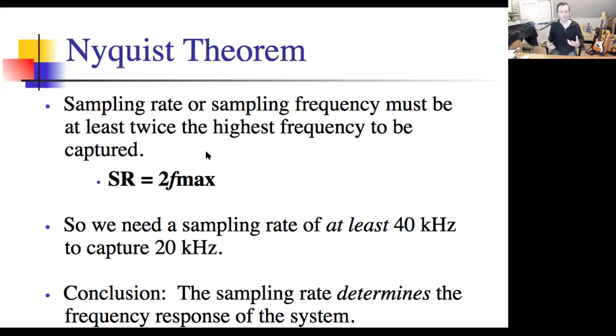Now, there are some studies that show that small children can hear up to about 22,000 hertz. Thus, we have a sample rate of 44,100, a little extra, hertz. And that's the sample rate for a CD. It's designed to be able to reproduce up to 22,050 hertz.